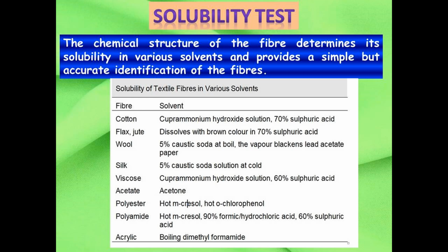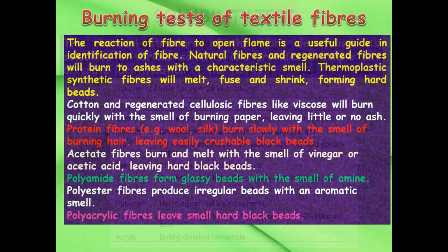Viscose: dissolves in cuprammonium hydroxide solution and 60% sulfuric acid. Acetate: dissolves in acetone. Polyester: dissolves in hot m-cresol and hot m-chlorophenol. Polyamide: dissolves in hot m-cresol and 50% formic or hydrochloric acid solution, 90% formic acid or hydrochloric solution, 60% sulfuric acid solution. Acrylic: boiling dimethyl formamide.